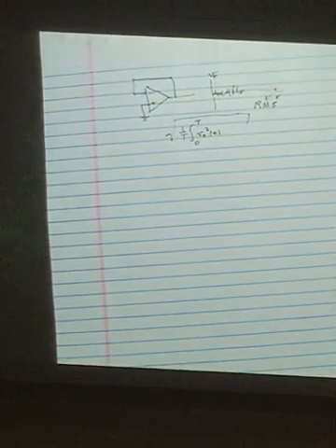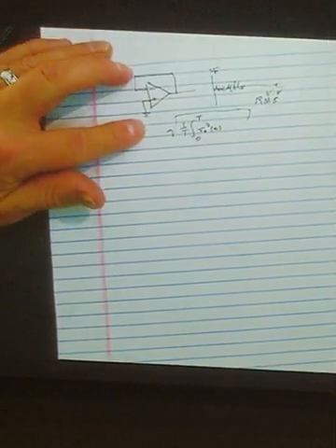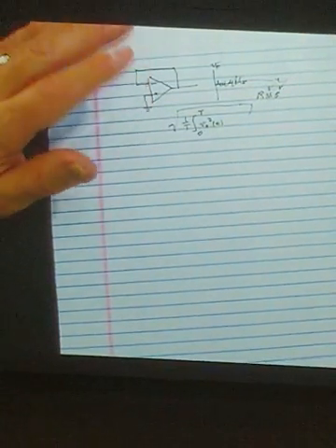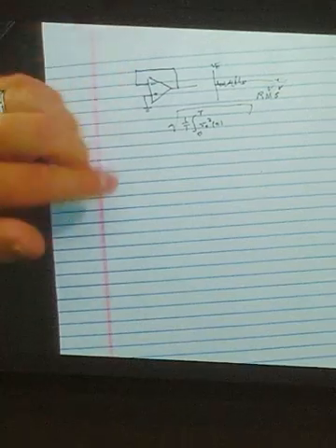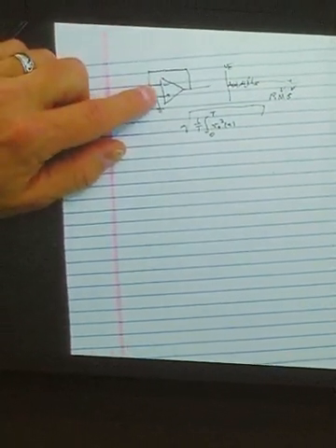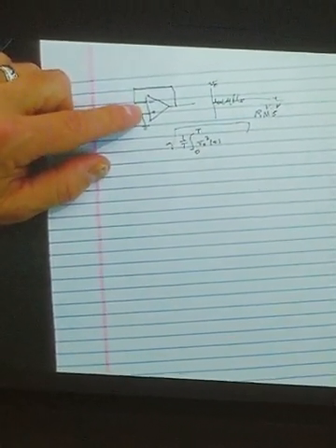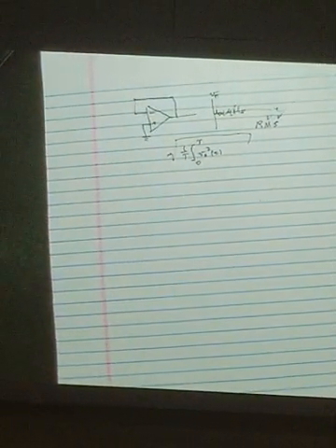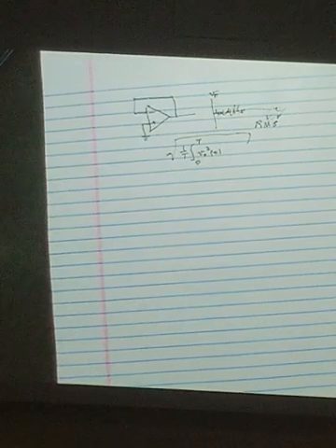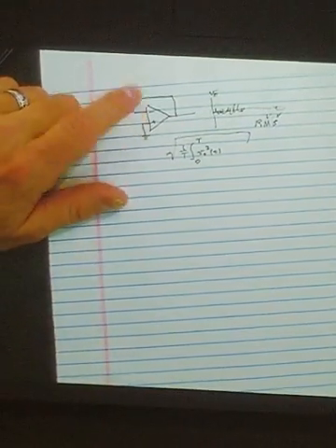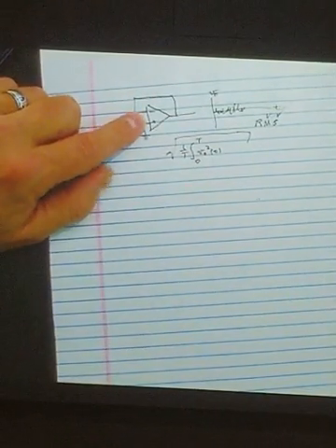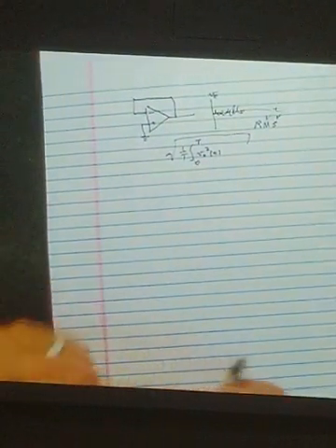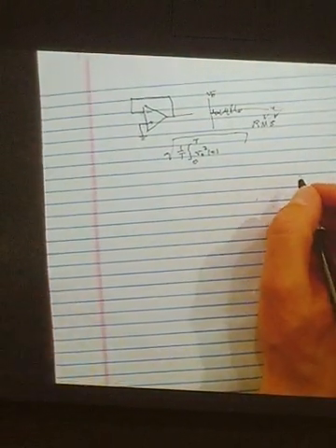We're talking about if you power this with batteries, hang capacitors off the power supplies, make everything as quiet as possible, there is still noise, and simply put, that's due to random collisions of electrons inside the various resistors and transistors inside of here. So can't do anything about it. You cannot eliminate it. It is always there.